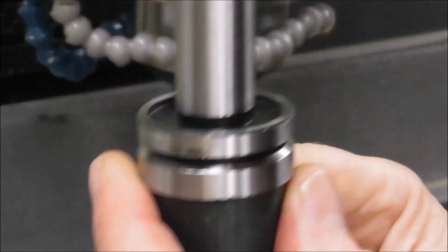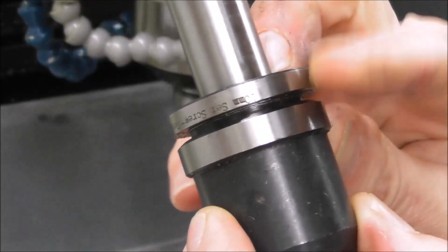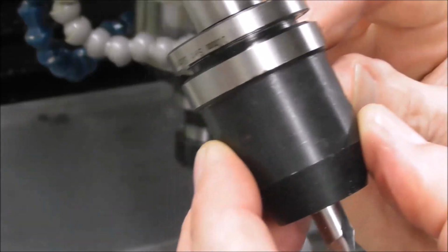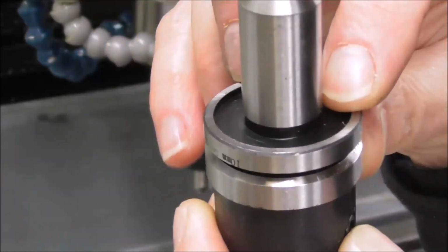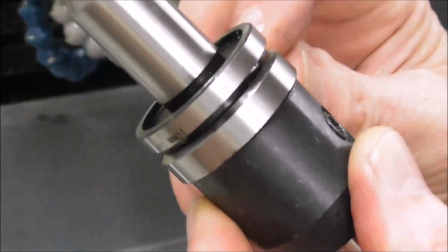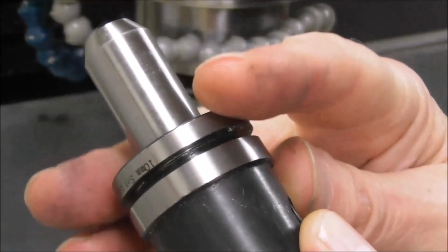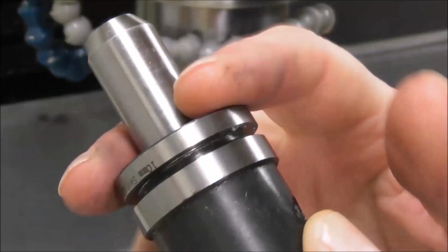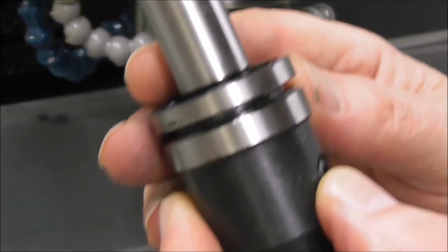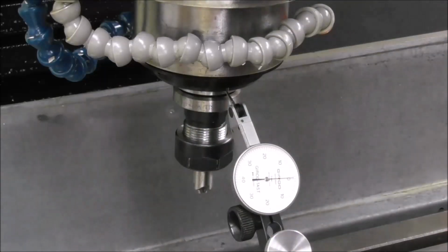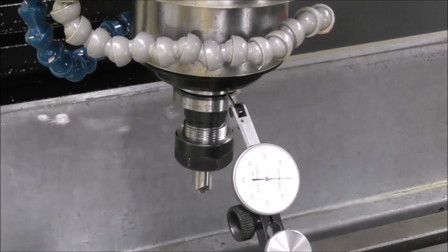If you have a look at the TTS flange, it's not a very rigid construction. It's a bit like a spring, and especially on the automatic tool changer slot versions, it's very hollowed out inside there, and there's a groove in here. It's not a highly rigid design, and so you're going to get some compression. This becomes a bit like a spring washer. So be aware that the TTS system is not a high precision system. We're getting errors there of about 1 thou, or 0.025 of a millimeter.